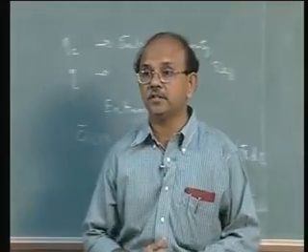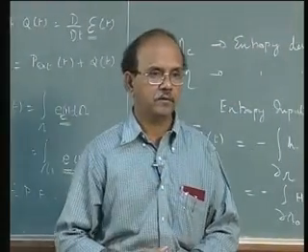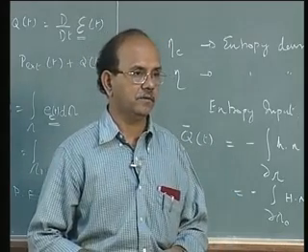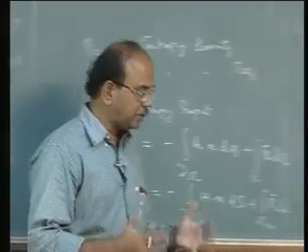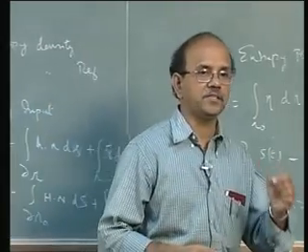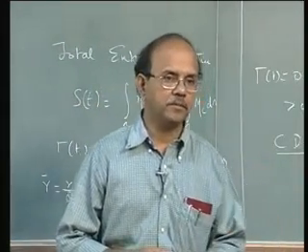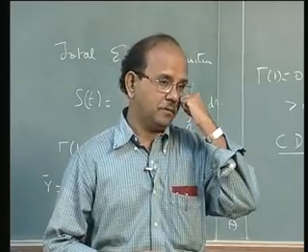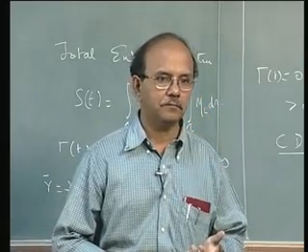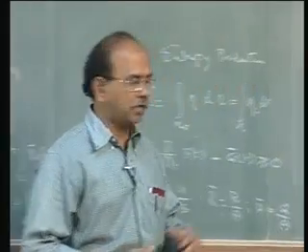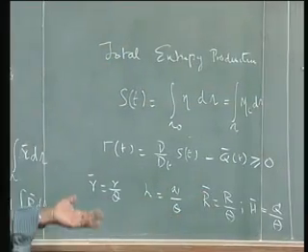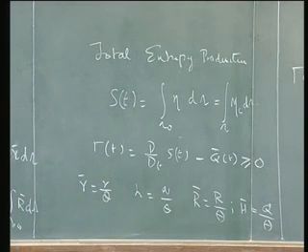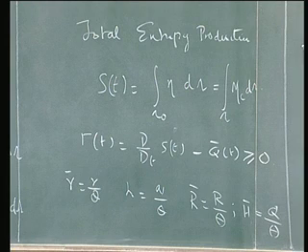So entropy is treated as a fundamental quantity, okay, and temperature is derived from entropy. But there are other approaches to thermodynamics where temperature is treated as a fundamental quantity and the entropy is derived from temperature. But in solid mechanics, thanks to Truesdell and his group, this kind of approach is followed throughout.